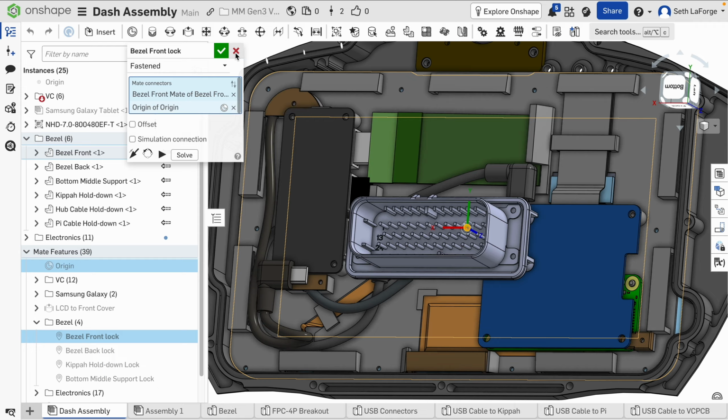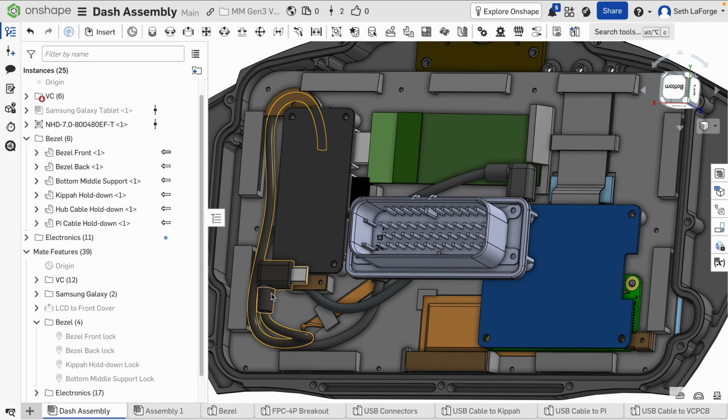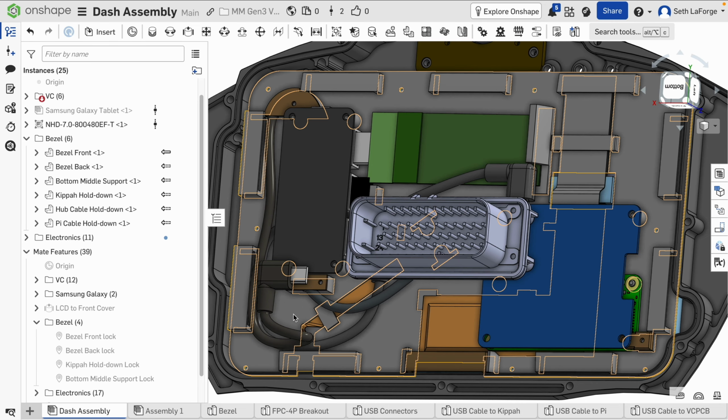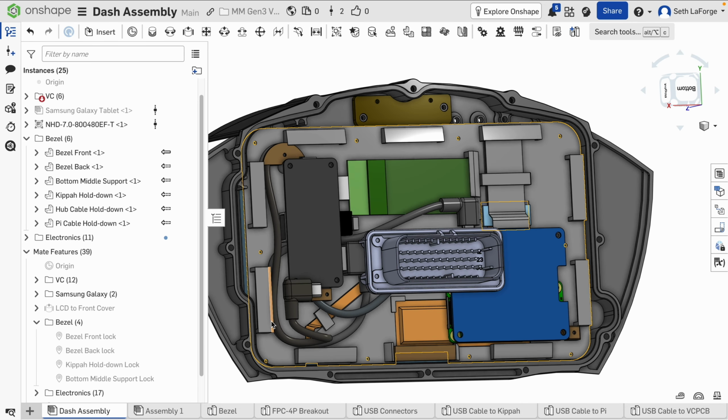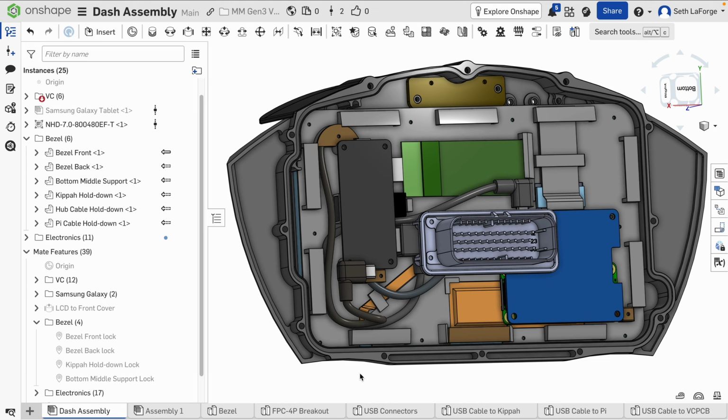In principle, there's these things, some parts that are created in context of an assembly. There's options that are supposed to lock it to the origin, but it just doesn't seem to work reliably. Anyway, I hope I'm giving the impression that editing parts in context and the configuration variables can be a really powerful way to create parts relative to existing parts. But it's a little hard to wrap your head around and a little complicated. Anyway, I hope that helps. Thanks.